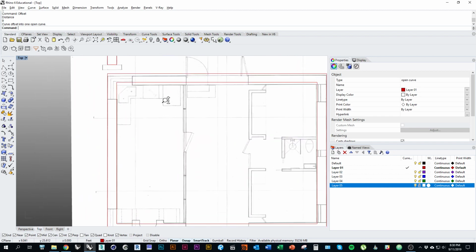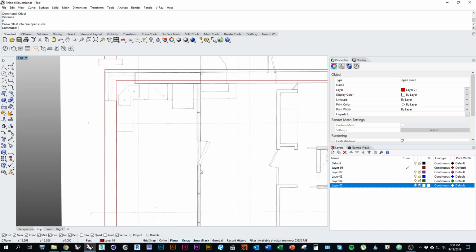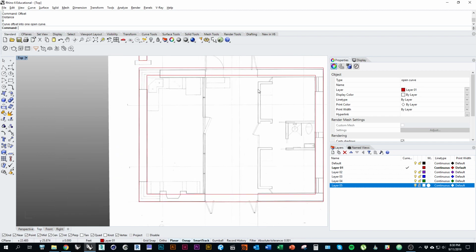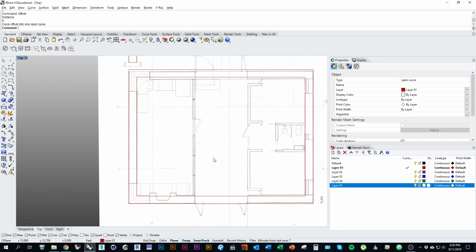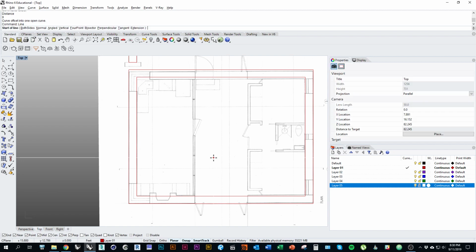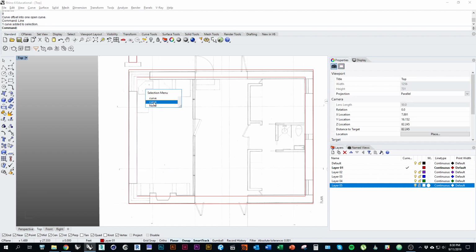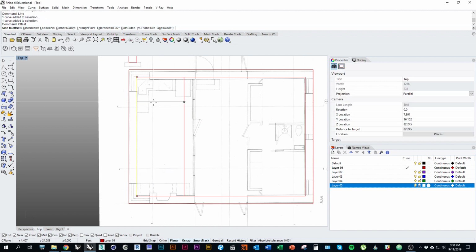Oh, and then one other thing we might do right now would be to draw the interior envelope, or the inside walls that separate the breezeway from the fully interior spaces. So once again, I would just draw a line. I could trace the inside of the interior wall. Select that line and offset it. Again, I'll just hit distance to kind of trace. So it looks like it's about 11 feet.